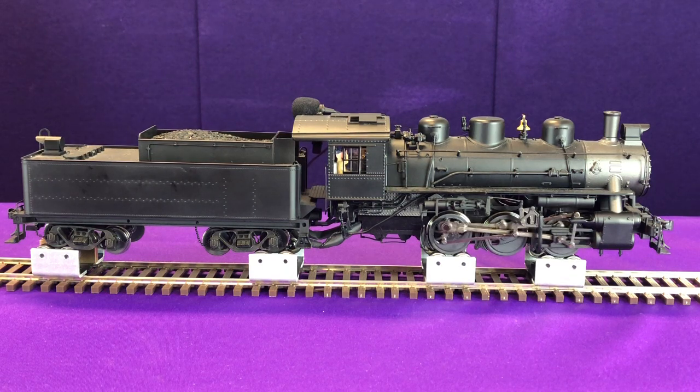The third part of this is CV2.512, and that determines how sensitive the decoder is going to be to changes in the load. It's defaulted somewhere around 60 or 64, I believe, which is a good number for our steam locomotive, but we can go ahead and set that higher just to enhance that feature. So I'm going to take CV512 now, and just to show you, I'm going to set it to 150. And now when I run my locomotive, we'll get going at speed step 10 here.